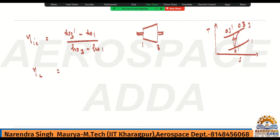I had given that formula in terms of temperature also. So Cp T03 dash minus Cp T01. If Cp is in the numerator and denominator, it will cancel. So what you will get is T03 dash minus T01 divided by T03 minus T01. If you remember, this was the formula, right? And this T03 minus T01, I told you, is the temperature rise, basically the overall temperature rise, okay?